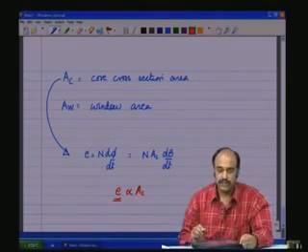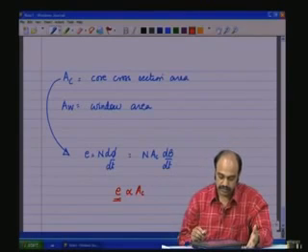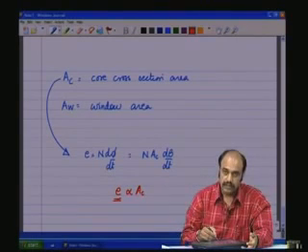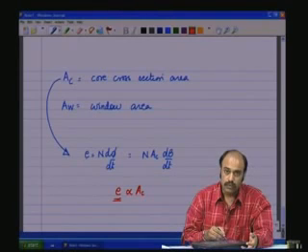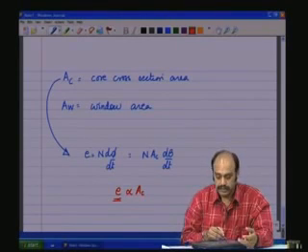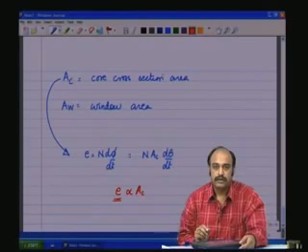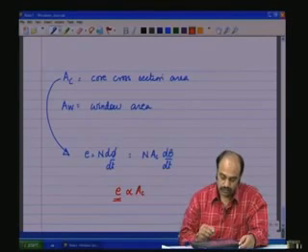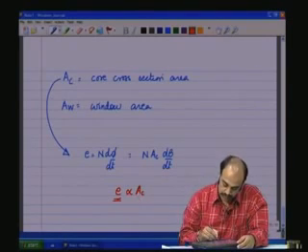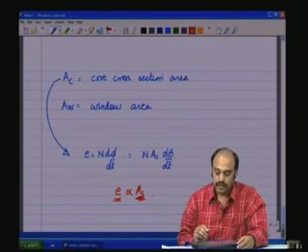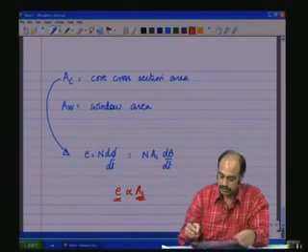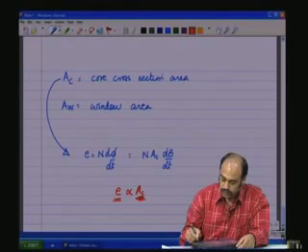How much voltage it can withstand, beyond which the transformer saturates, because beyond which the volt second product will exceed the flux density capability of the core, and the core will saturate. So, AC will tell you how much voltage a particular core can withstand.